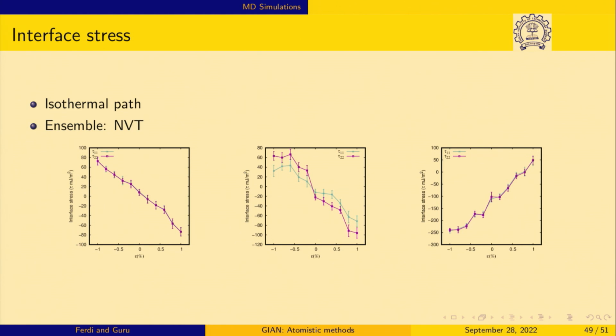We also did some comparison with phase field crystal modeling of the same quantities, because there it is far easier to evaluate these quantities, and we matched trend-wise, given that phase field crystal makes this iron lattice with 2 parameters, much like LJ. We thought that this is really great. The trends were the same, but the numbers did not match.